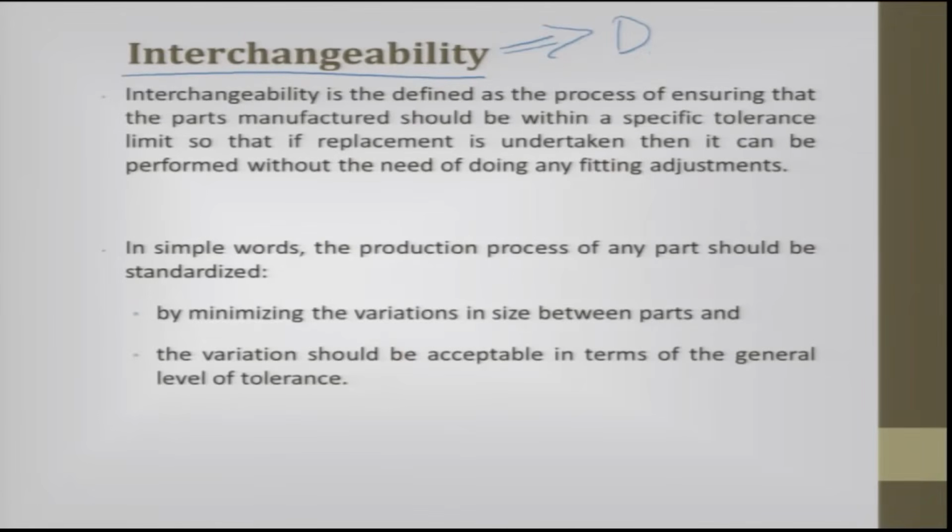And this concept is very important when we talk about design for manufacturing. As much as possible, when you try to develop a product, try to use standard parts, such that for those standard parts you will always have vendors who will be competing and giving you a price which is economical. Two, you do not have to depend upon one source, you can have multiple sources. So, the advantage is you can make your product more economical and you can make your product very quickly.